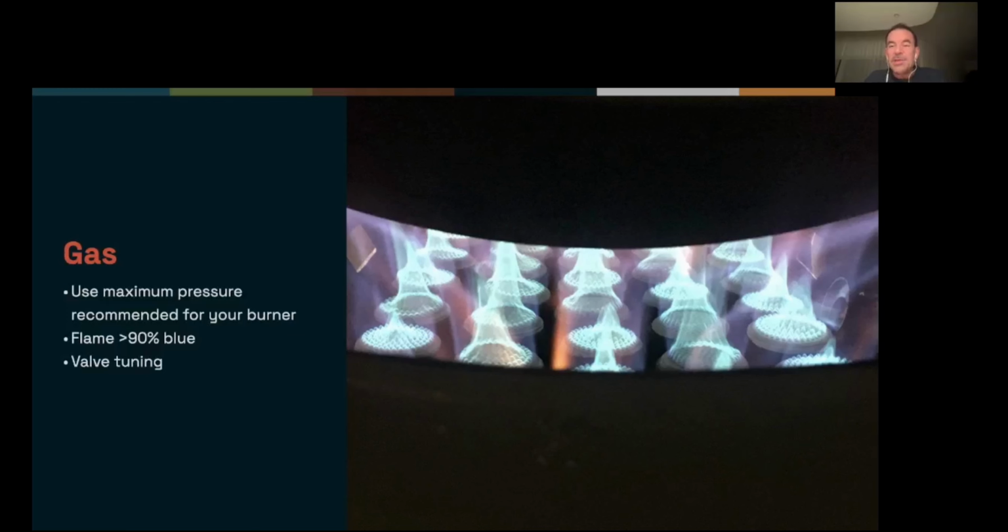I wouldn't worry about this unless you feel like you're in one of two situations. One, you have the maximum allowable pressure for your burner, but yet your machine still seems a little bit underpowered. Or two, no matter how low you go with your gas settings on the control panel, your ROR tends to rise before you reach first crack, and then you tend to see a pattern of the ROR rising and crashing and rising again. If that happens despite using very low gas settings going into first crack, then it may be that you need to tune your burner. And it's a very easy process. It usually takes less than 5 minutes.